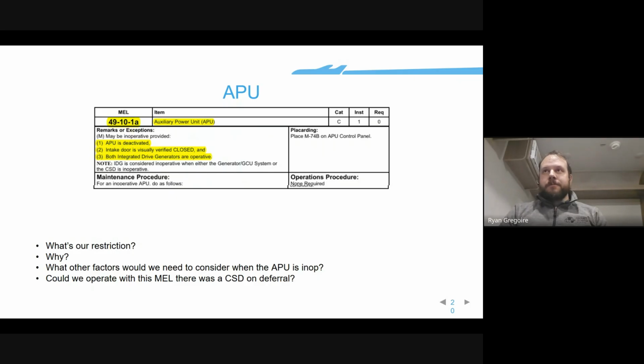If you dispatch a flight and it diverts to its planned alternate, and you didn't plan an alternate with ground power and an air start for an aircraft with a deferred APU, you're going to look a little foolish and probably be writing an ASAP report as to why an aircraft got grounded after diversion to a planned alternate when it had a known APU deferral.